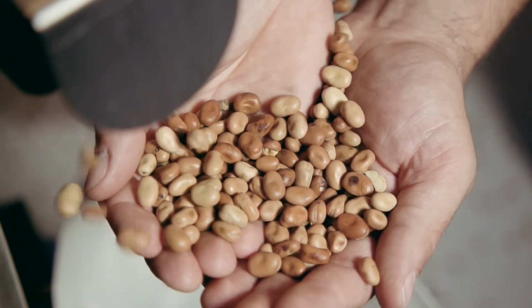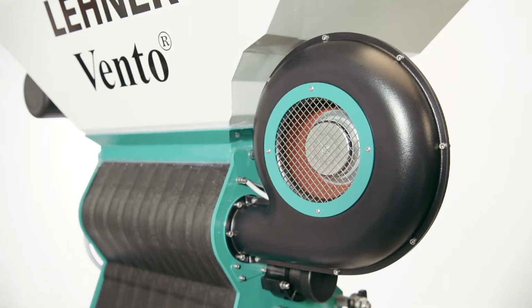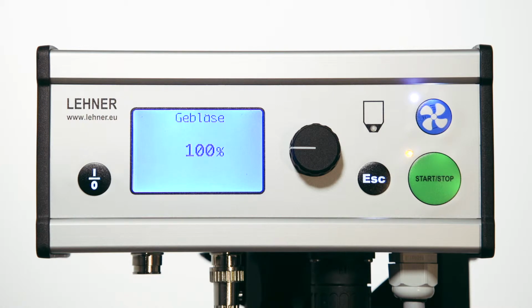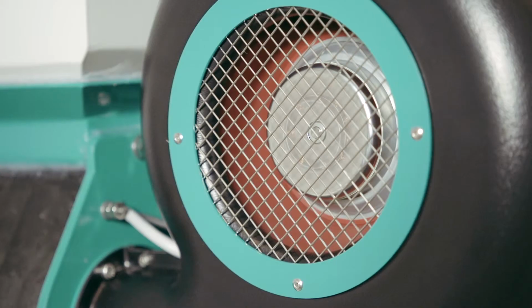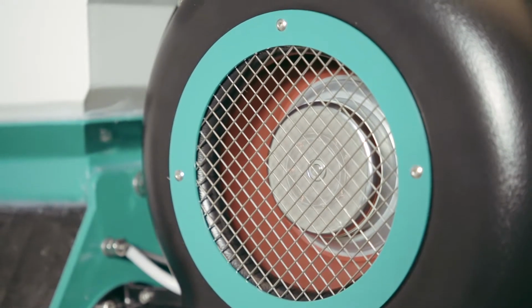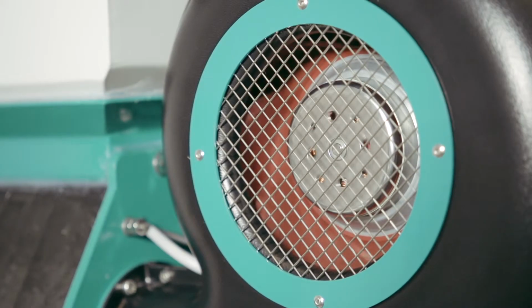The fan is controlled from the control panel. Push the blue fan button to start the fan. The speed of the fan is fully adjustable relative to hose route layout and material to be dispensed. The fan is designed to start up slowly, building up to maximum speed to eliminate potential voltage issues. This is shown by the LED on the fan button flashing white, and once preset fan speed is reached, the light turns blue and remains constant. To switch off the fan, press and hold the blue fan button for 2 seconds.